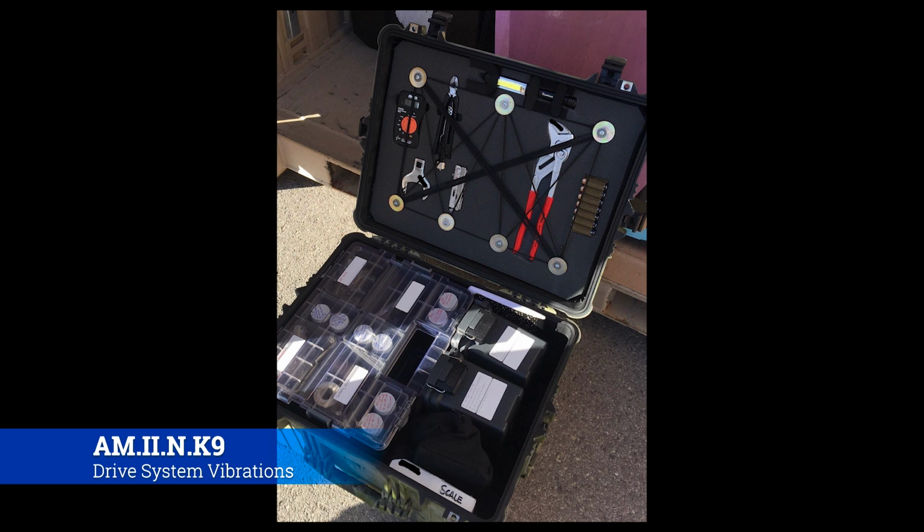Now, every rotor blade has a certain weight to it, usually in grams typically. So let's say you have one rotor blade on a two blade head that's 500 grams, and you have another one that's 450 grams, and you install it, you don't install any extra weight, and you turn it on. That is going to shake that helicopter to death. So what you have to do is go back and put 50 grams on that 450 gram blade to level it out and make it work appropriately.